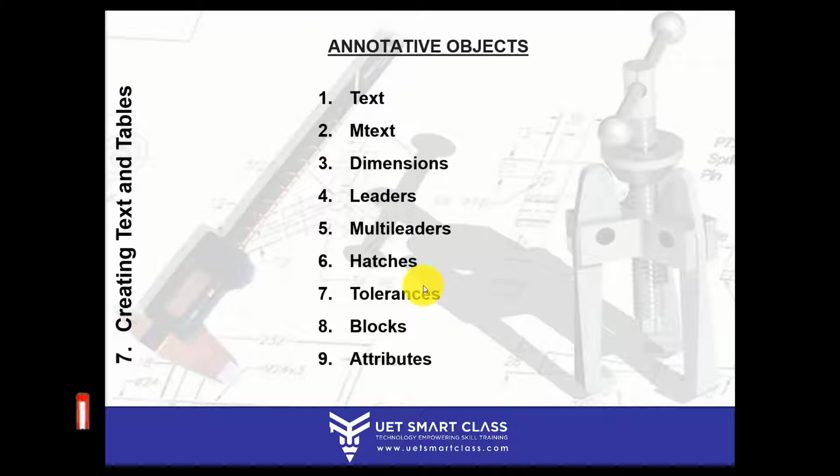That's why I said every object in your drawing which is not a model or geometry is an annotative object, right? So all these objects have an annotative property with them. This property basically allows you to use that process of automatic display. So there is this automatic process of display wherein, whatever scale you desire on paper, you can see on your model space as well. This annotation property was added in AutoCAD 2008.